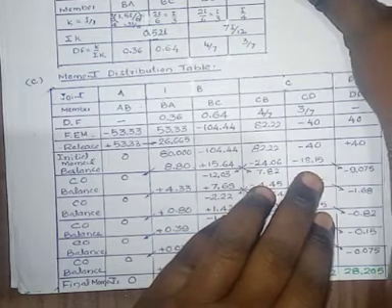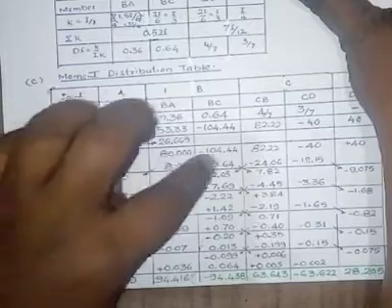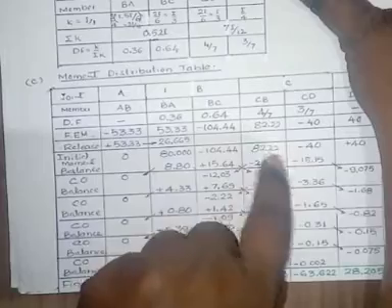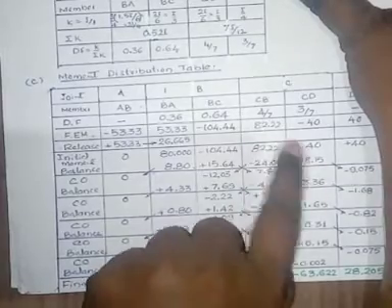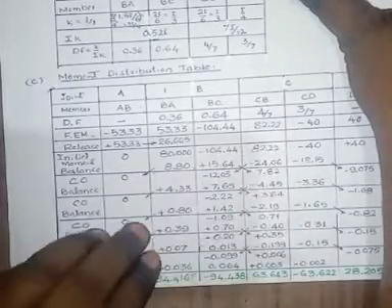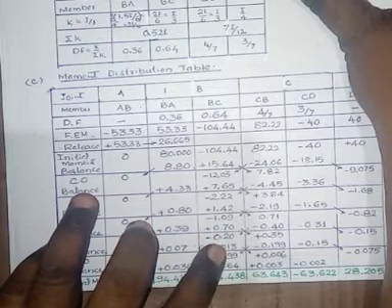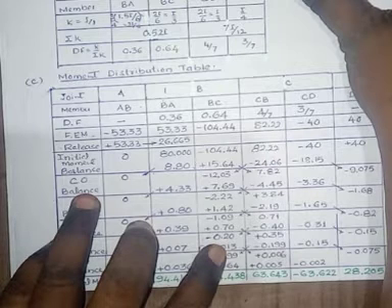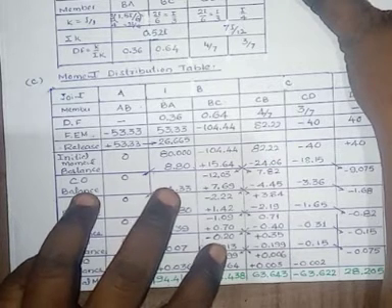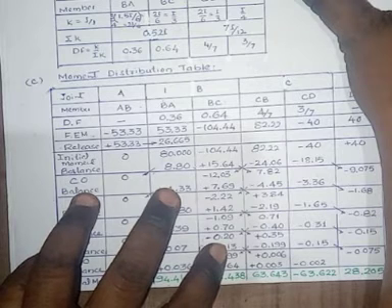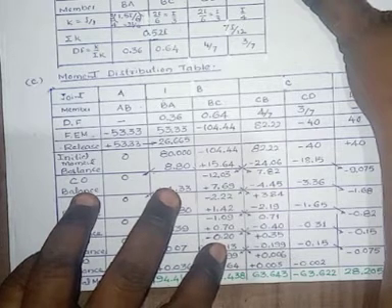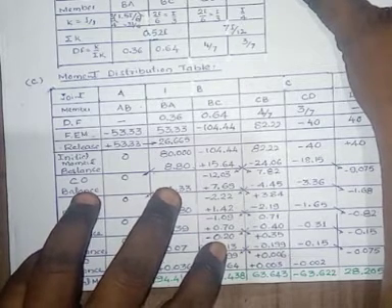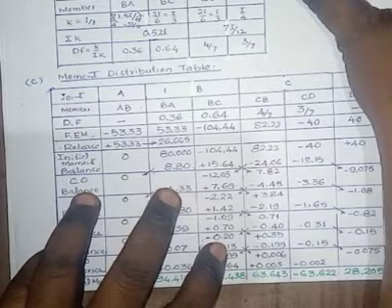Here this process is known as balancing. Here by observing these four values, the summation of these four numerical values at joint C must be equal to 0. Now carried over: if the end is fixed, from the preceding support carry the moment. If it is carried, 50% of the moment is carried. If the support is the end support with simple roller or hinge, no need of carry over.